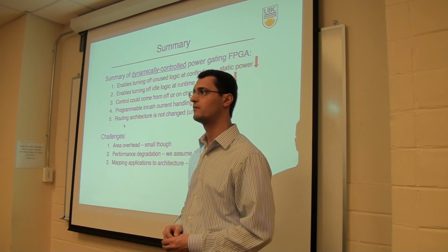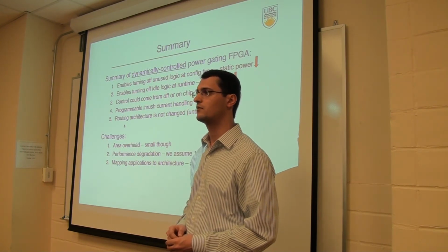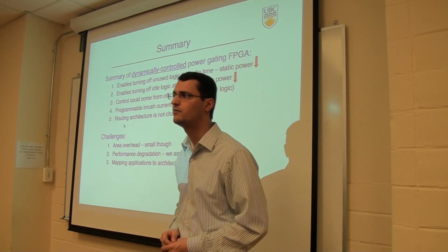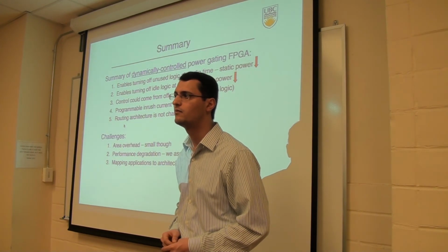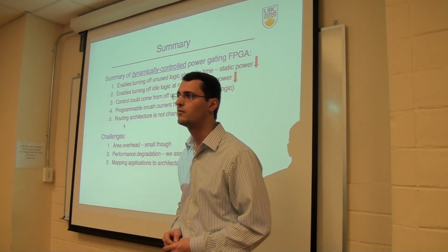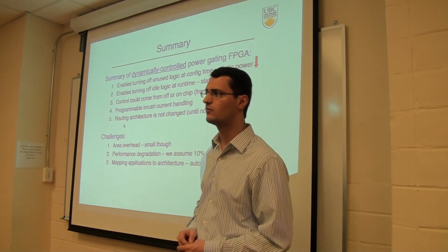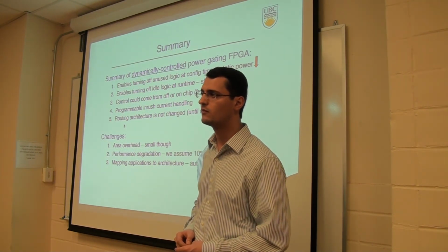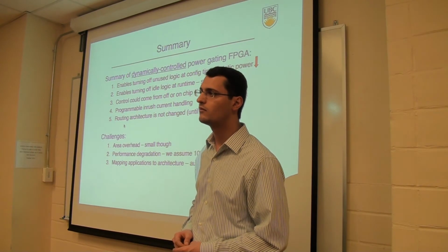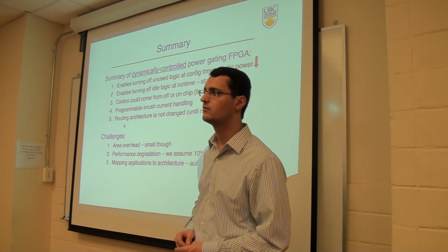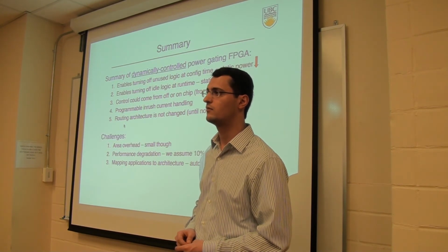What do you assume about switching activity when you're sizing your power switches? When you're resizing your power switch for regions of various sizes, those regions will all have different dynamic power requirements.